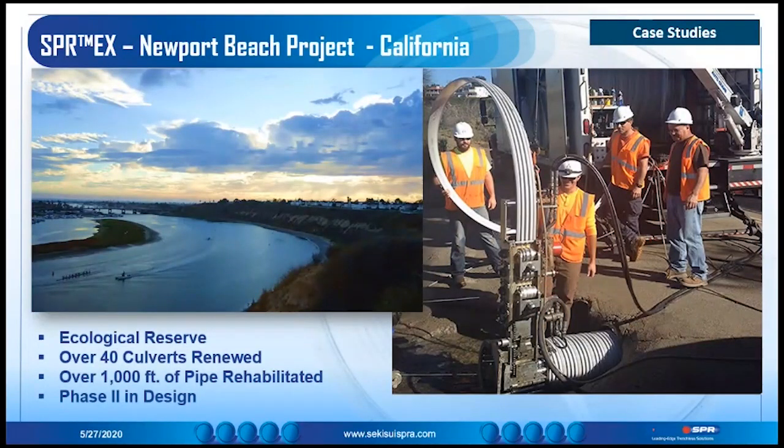Now, I mentioned to you the environmental aspects of our liners are very important. This was a project for the city of Newport Beach in the Back Bay area. It was an ecological reserve. It originally had been specified with CIPP. The contractor was actually quite concerned about using a styrene-based lining solution in an area with open tidal waters with a potential for contamination. Our contractors, Vertec, New Line Technologies, were able to install our liners in open flow, did some tidal flow management, but there was absolutely no site contamination using our product for this particular application.